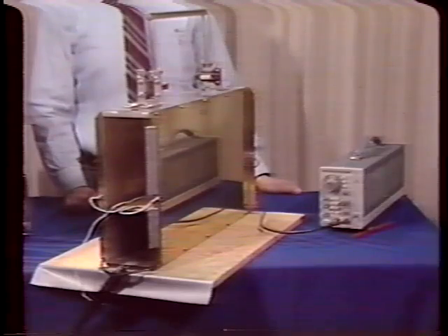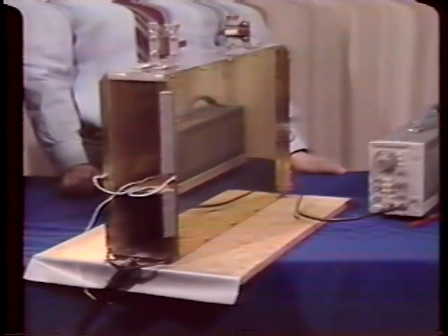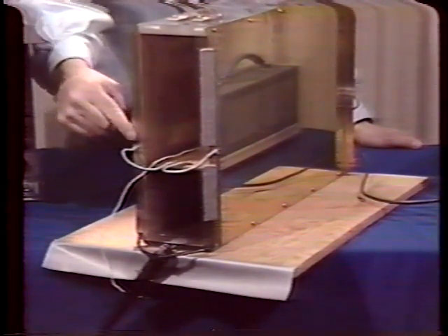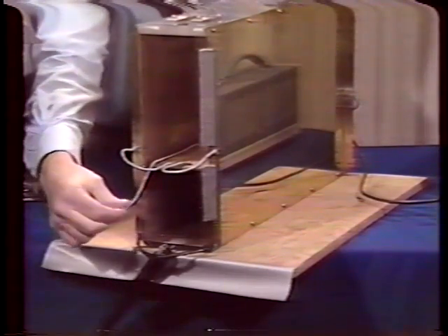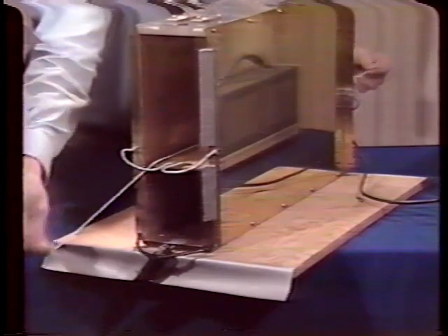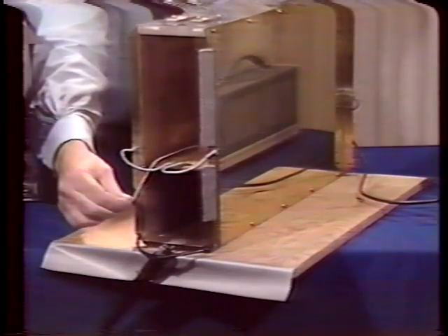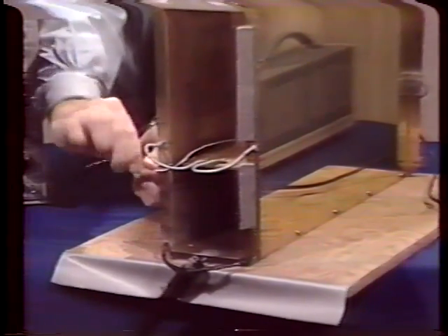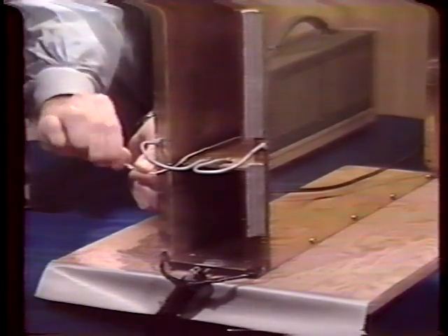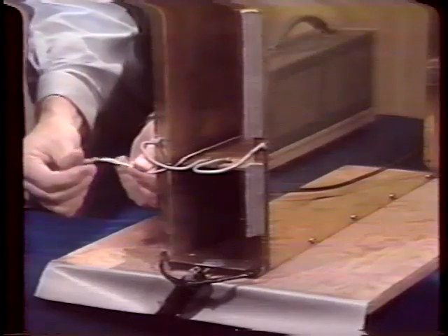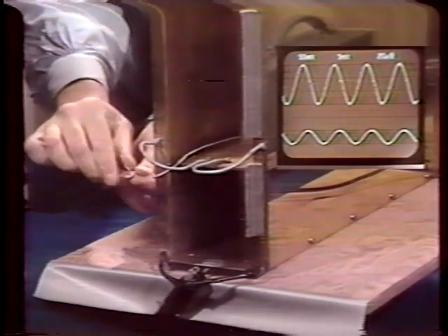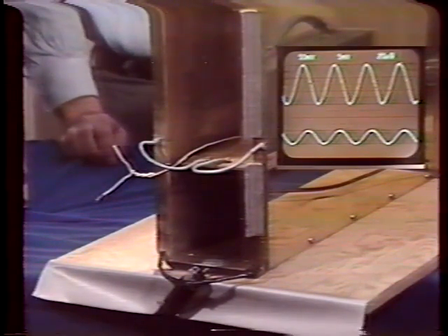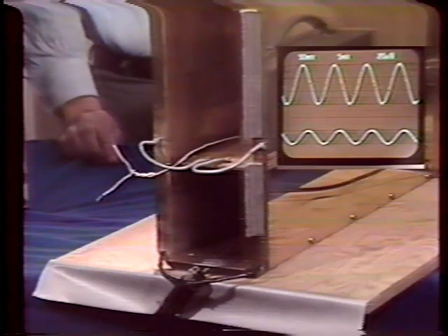To see this, we can use a loop of wire rather than the terminal voltage to measure the flux through the gap between the upper electrode and the left wall. The loop passes along the outer edge of the upper electrode and is returned just outside the adjacent conducting wall. So arranged, it links little extraneous flux at the ends. Also, because it will be connected to the high impedance of the scope, it carries a negligible current, and so the integral of the electric field intensity around the loop, which is the voltage at the terminals, does not have a part due to the resistance of the loop.